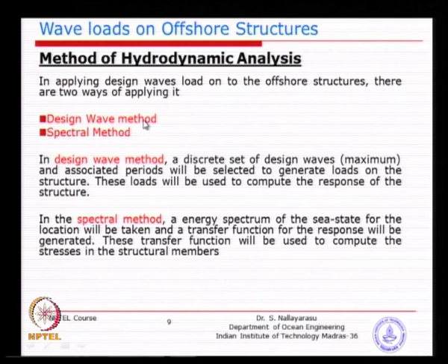So, the design wave method is basically going by the design for the maximum wave that may occur at the site during the design period, or the life of the structure. That is called a design wave method, which is slightly conservative, because you are not taking into account the probability of the occurrence of that particular wave.